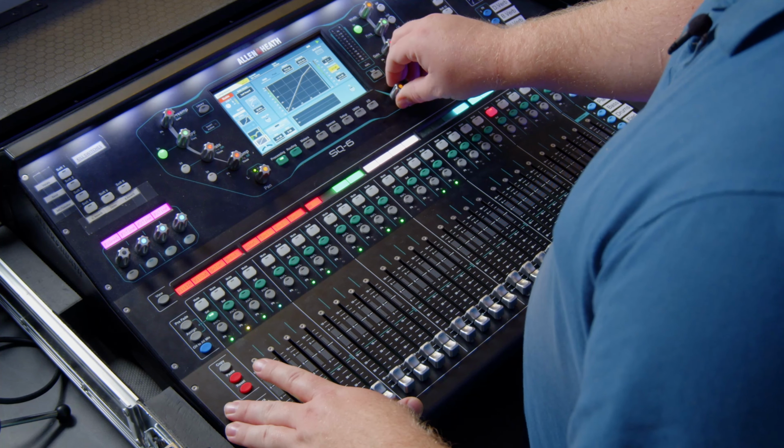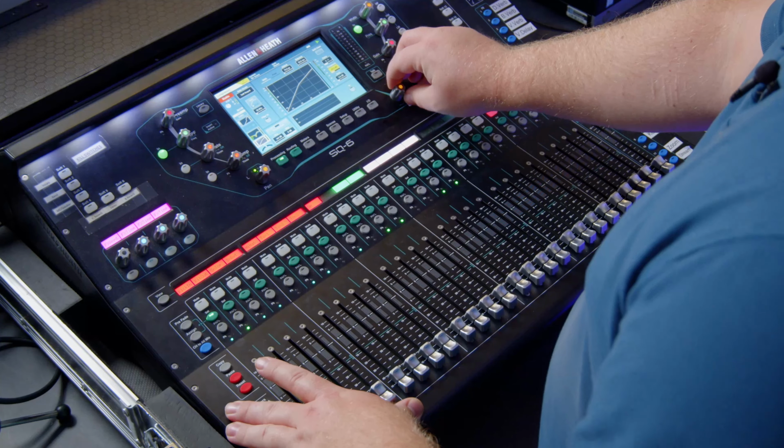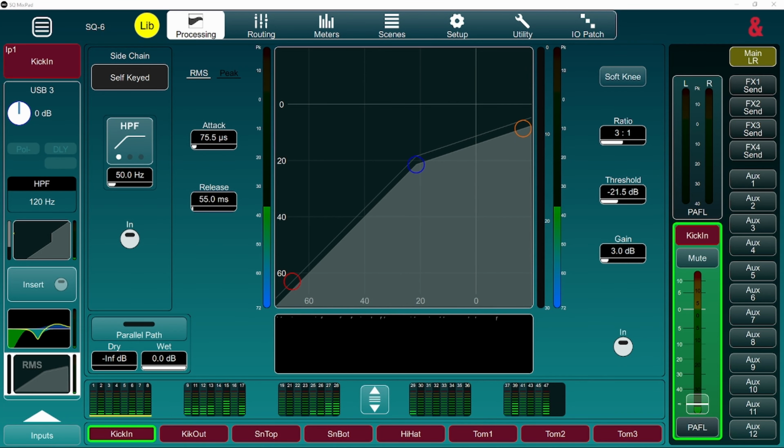At the top, there's also an option for soft knee. So if you can see on our graph here, there's a spot where the graph bends over, that's our threshold, and it's just immediately 5:1, or in this case 6:1, at that point. But if I turn on soft knee, it rounds it out. So you eventually get to the 6:1, but everything before that point will be less and less of a ratio until there's no compression. So you'll end up doing more compression, but just at a reduced ratio until you hit that point.